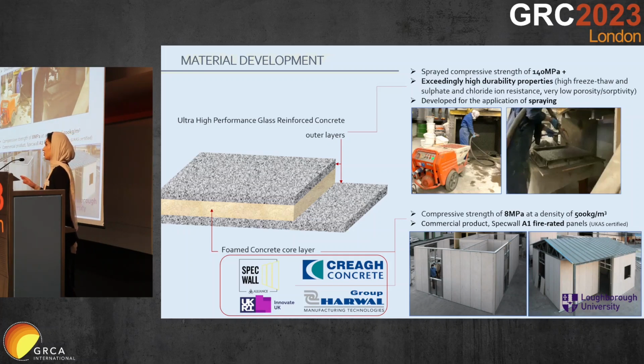So I know there were a few questions about the long-term performance of UHPC earlier on. There are abundant academic studies that prove the durability properties of UHPC. We've done some personally as well, so we assessed the freeze-thaw susceptibility of this material. We also did the sulfate and chloride penetration test and also water ingress test to assess whether actually they are durable long-term or not. And the results came back very positive.